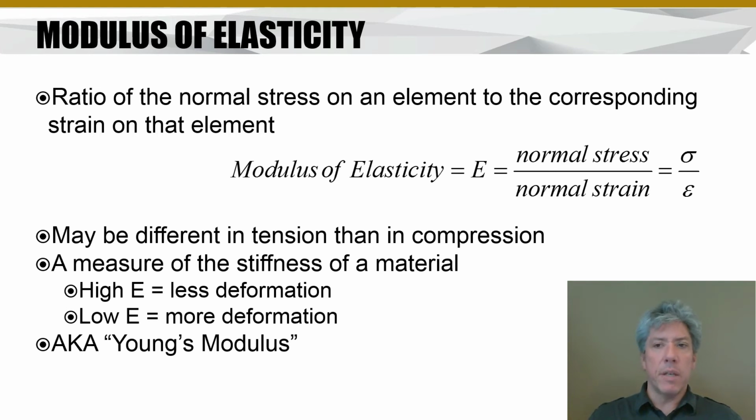Now be careful about the units here. Stress has units of, say, PSI, pounds per square inch, or gigapascals, megapascals, pascals, whatever you like. Force per area, basically. And notice that strain is dimensionless, and so the elastic modulus always has the same units as pressure has, although really technically it's a related but different dimension, because we're talking about it in a solid, not in a liquid or a gas.